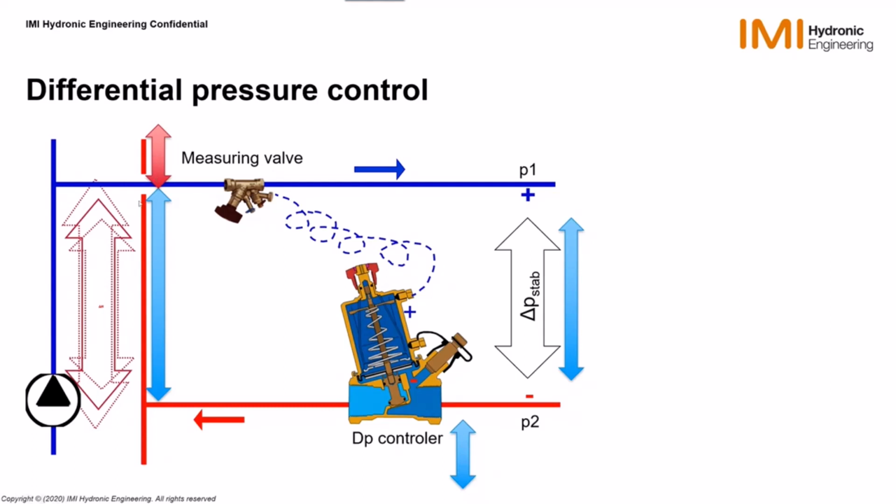And at the speed of sound, the increase of pressure is propagating and will induce an increase of flow, and therefore pressure drops everywhere. So every one of these previous pressure drops will increase by the same percentage as the available differential pressure before this delta P controller has the time to react. And here I am forcing the explanation a little bit.